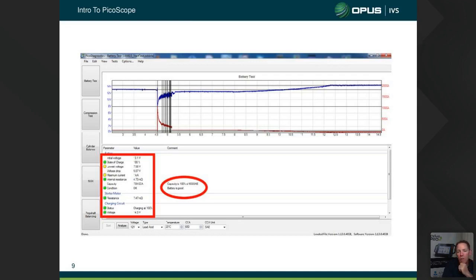And we actually have 2 channels. So we have a channel here for voltage and a channel for current. And we can see that they should mirror each other. The cranking current goes up, and that's in the red. So as we hit that breakaway of the crankshaft starting to spin, the current flow out of the battery is at its peak. But that's also when we get the biggest voltage drop out of the battery. We see our battery voltage sitting up here at 12 volts, and we see it drop down. And these two should mirror each other.